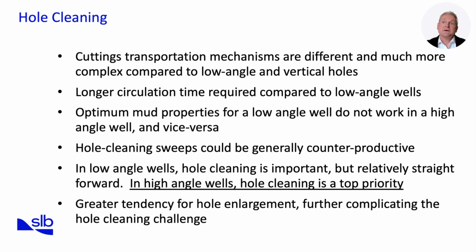Hole cleaning is one of the most critical challenges in extended reach drilling. In ERD wells, the cuttings transport mechanisms are significantly more complex compared to those in vertical or low-angle wells. At high inclinations, cuttings tend to settle on the low side of the hole, creating beds that are difficult to remove. Circulation times are longer than in low-angle wells, meaning it takes more time to bring cuttings to surface. This delays feedback and increases the risk of build-up.